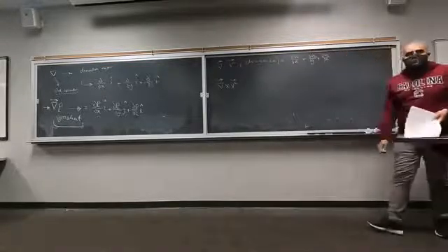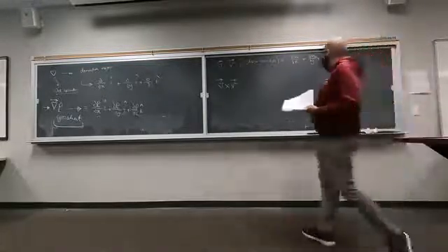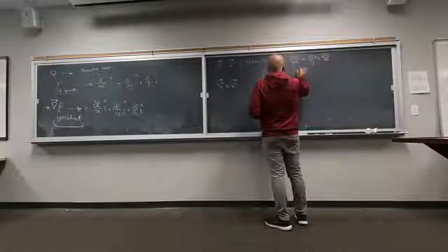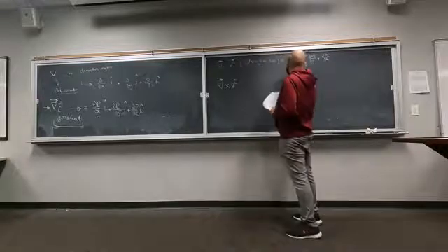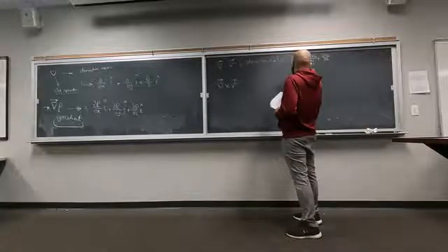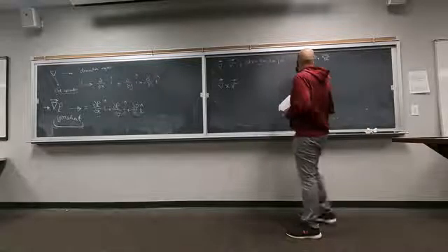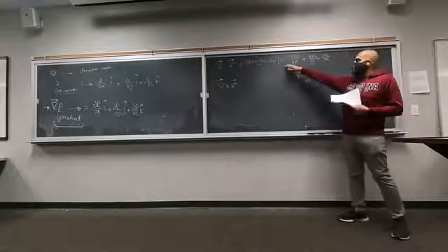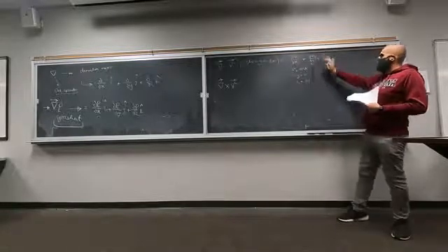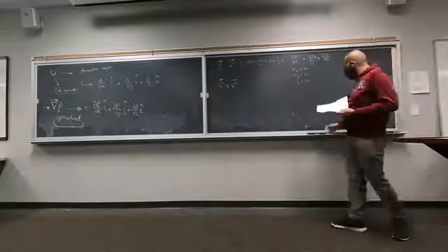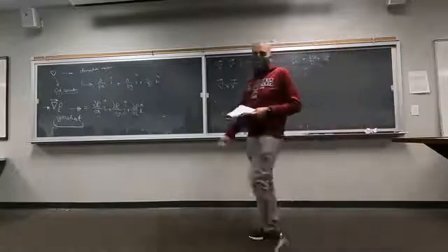In aerodynamics in general, for vx we use u. So the component of velocity in the x direction is u, in the y direction is a small v, and in the z direction is called w, right? So essentially, this divergence is going to be partial u partial x plus partial v partial y plus partial w partial z. Okay. What about this next operator?